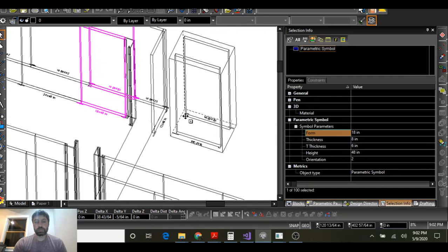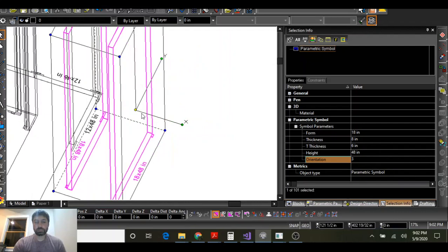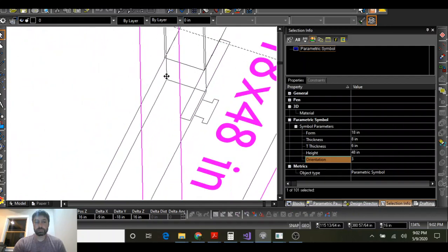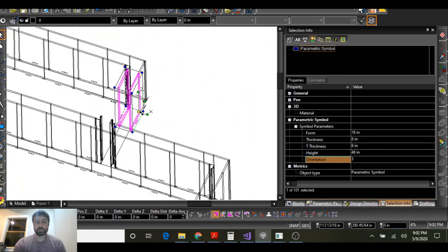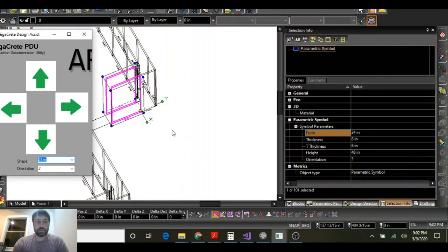We'll pick a spot to demonstrate a shelf. If we want to make a drop in the footer, go down, then back up. This gives us the ability to discuss the form design.